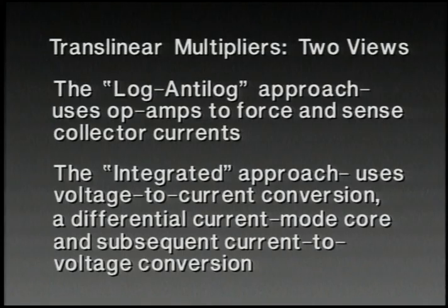Let's now talk about probably the most popular application of the translinear principle, and that's translinear multipliers. There are really two ways that we can view translinear multipliers. In the traditional view, we would speak of the log-antilog approach. Log-antilog multipliers go back many years, probably to the very early days of bipolar transistors, and traditionally use operational amplifiers in a fashion similar to that I've mentioned already to force and sense collector currents.